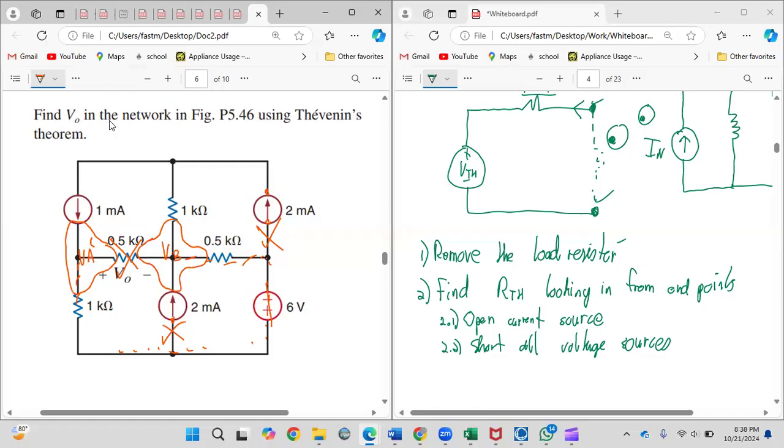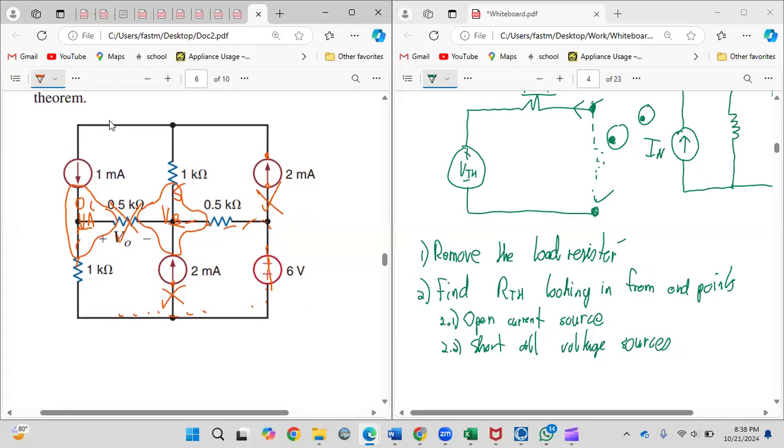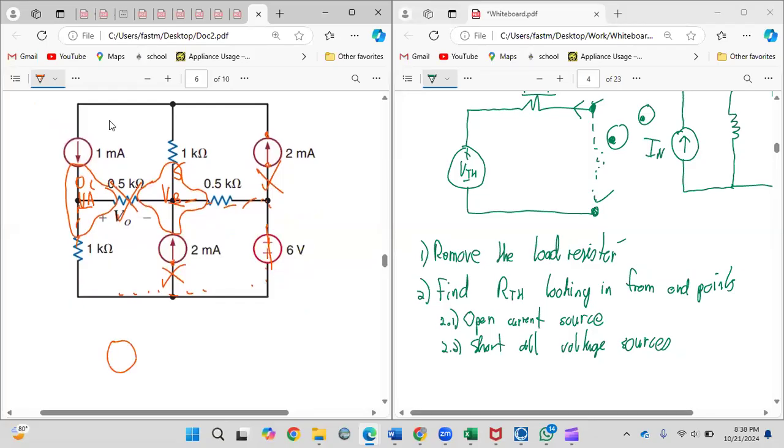And if you want the voltage here now, you will already have it, because if VA is here and VB is here, and you want to know the voltage across it, won't it just be VA minus VB? So if there's 10 and there's 5, it would be 5. So just like that, you have your V Thevenin, you have R Thevenin, which would be 1.5 kilo ohm. You clearly see it's 1 plus 0.5. And then you put back in the load that I gave.